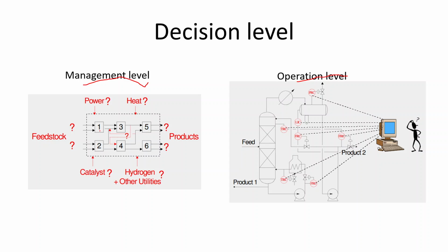So this unit 1, for example, is characterized as a simple type of product. If we have a feed A, feed B, and feed C, and we mix feed A with feed B in different ratios, they already know the yield functions of those. So knowing what type of feed and how much of each, and how much power or heat for this unit 1, they can calculate the typical outputs of unit 1, and then use those outputs to enter unit 3.